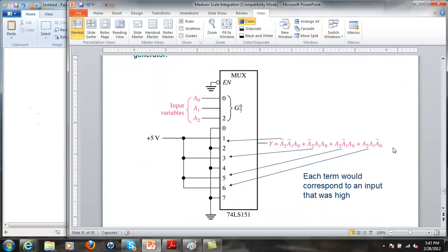Okay, here's a multiplexer used in that configuration I just mentioned with a static input. I can basically make any kind of combinatorial circuit, at least with 3-bit input, that I want.